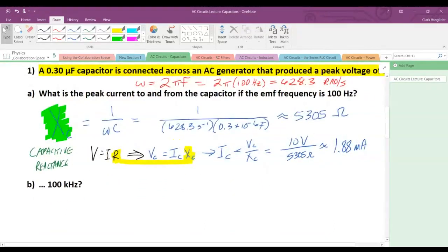All right, so not hard, but not as straightforward as the DC circuit stuff, because the impedance takes us up a little bit higher viewpoint, and we have 3 kinds of impedance: standard resistance from resistors, but then the resistance that capacitors and inductors have in terms of their reactance value, which we have an X sub C and an X sub L in there.